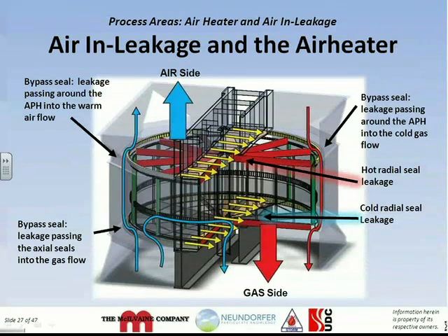Greater leakage rates mean more heat needs to be applied to the air entering to keep the cold end baskets above the acid dew point. When the boiler efficiency is calculated with a corrected to no leakage basis, flue gas exit temperature, the corrected temperature will be significantly higher when the dilution is accounted for. Just as an example, if the corrected to no leakage temperature is, say, 35 degrees Fahrenheit above normal or design, then this represents a full percentage point in efficiency penalty.